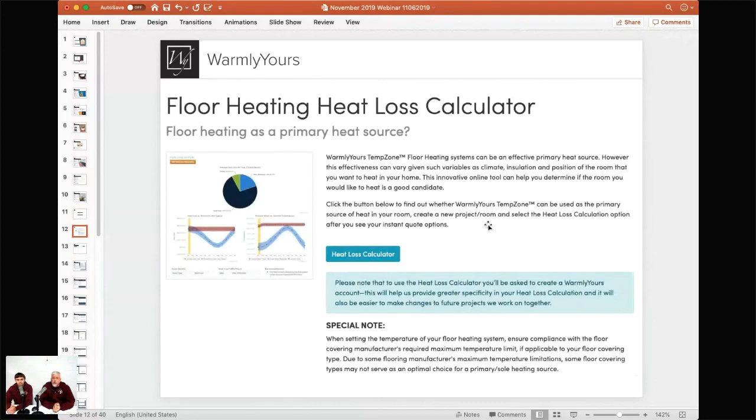If new construction, what is the best value for subflooring? Concrete slab with insulation on top? I don't go out and buy subfloor materials all the time. We can tell you what it costs for the heating materials, but I don't know what concrete sells for in your neighborhood. But the idea here is you want some sort of subfloor where it is not going to steal the heat. Yeah. And if you are going to use a concrete slab, the insulation needs to be on top